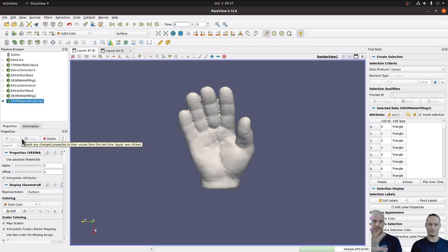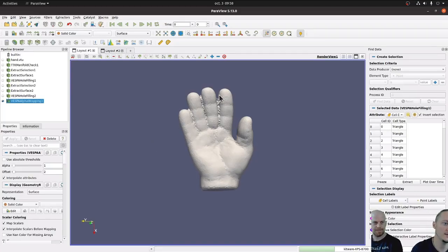So here the original topology is not used at all, right? Only the points. The points and the cells, because the cells are also constraints for the algorithm to respect, so it cannot push in between the points if there is a cell. Okay. So those are walls basically on which you can't go through. That's why it's different from Delaunay. Okay, got it. And here you can see with the current attributes that I have kind of large triangles and a large offset too.